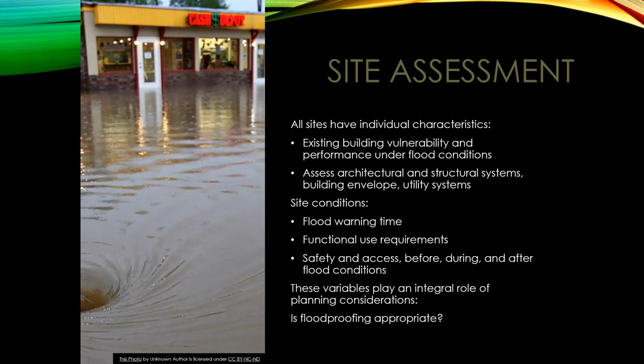withstand the floodproofing itself. So that could mean reinforcement and adding on mounting equipment for panels and flood shields to go on. So it can be stressful on the building already. So that's why we have to understand the architectural and structural systems of the building envelope, including utility systems, whether they can be elevated or if they can be designed to be submerged and then work after minimal cleaning and